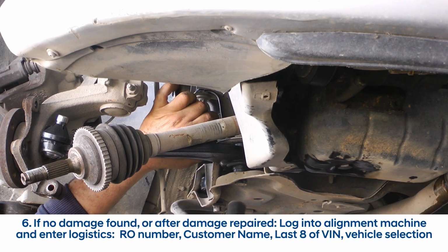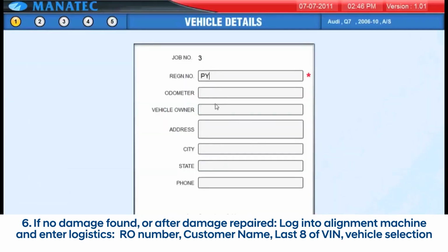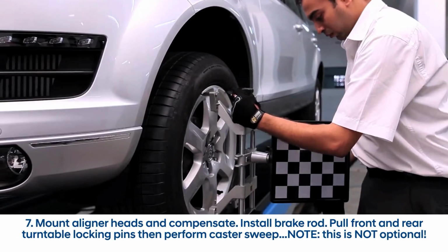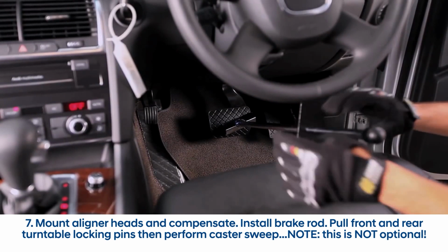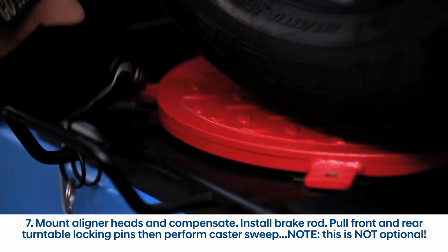6. If no damage found or after damage repaired, log into alignment machine and enter logistics, RO number, customer name, last 8 of VIN, vehicle selection. 7. Mount aligner heads and compensate. Install brake rod, pull front and rear turntable locking pins, then perform caster sweep. Note, this is not optional.